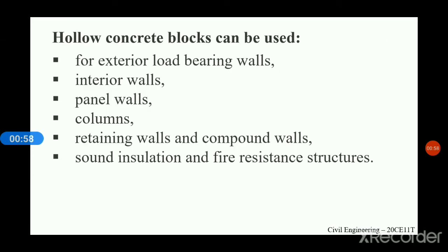Hollow concrete blocks can be used for exterior load bearing walls, interior walls, panel walls, columns, retaining walls and compound walls. Finally, the main advantages of these hollow blocks are sound insulation, fire resistant structures, heat insulation, etc.